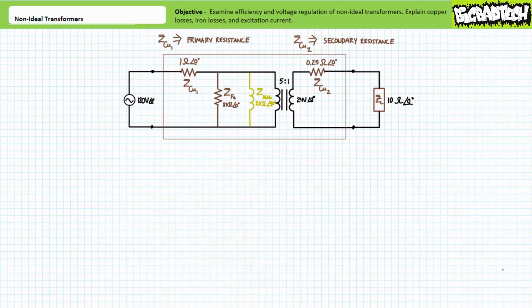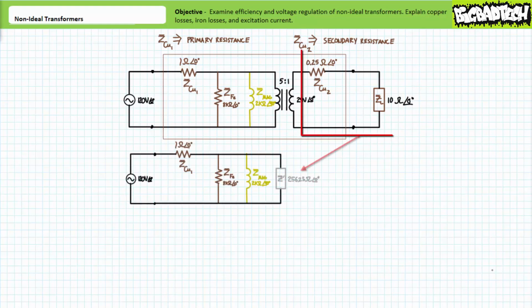Given we've included series resistances in both windings, we might expect these resistances to drop a small amount of voltage and as such dissipate a slight amount of power considered a loss to our larger system. Let's see if this is the case. Using this more complicated model necessitates a slightly more advanced series parallel analysis. Let's use the reflected impedance seen by the primary winding.